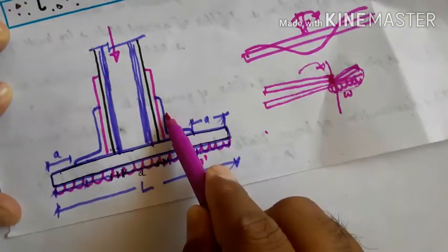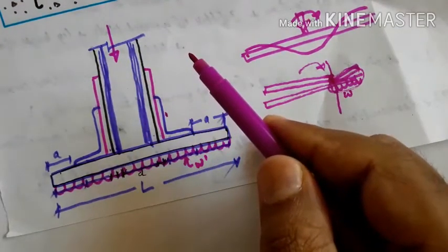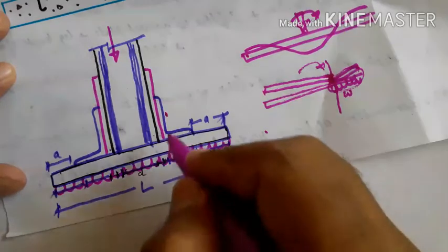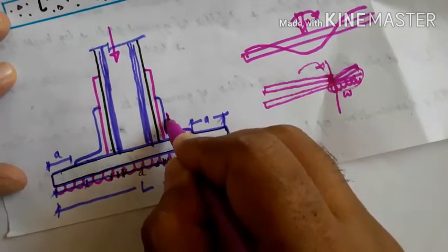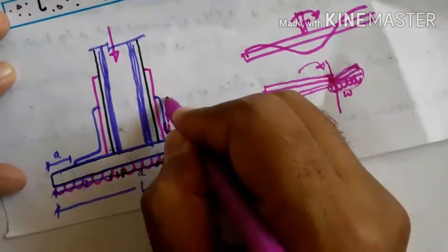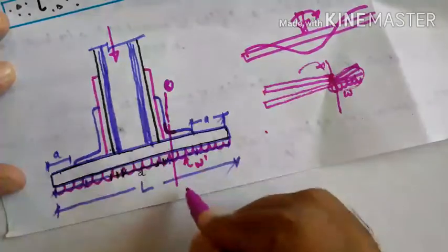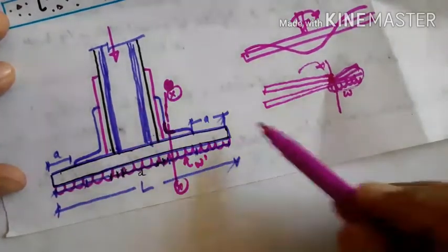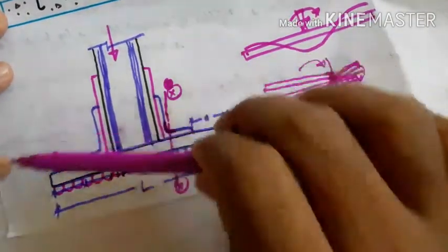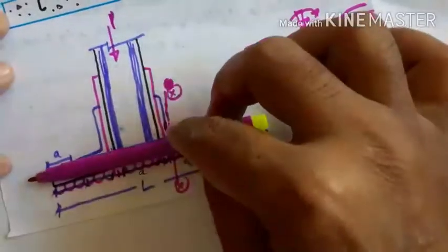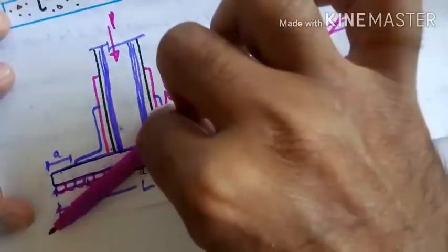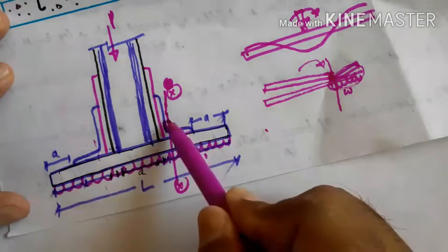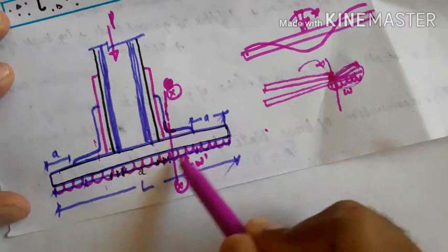Considering this, the critical section is assumed to be lying at the root of the fillet of the angle section. This is the root of the fillet of the angle section, and this is the most critical section. Say XX is the critical section, because the plate may get lifted up like this because of the heavier pressure acting. When this side may get lifted up, this will be most critical.